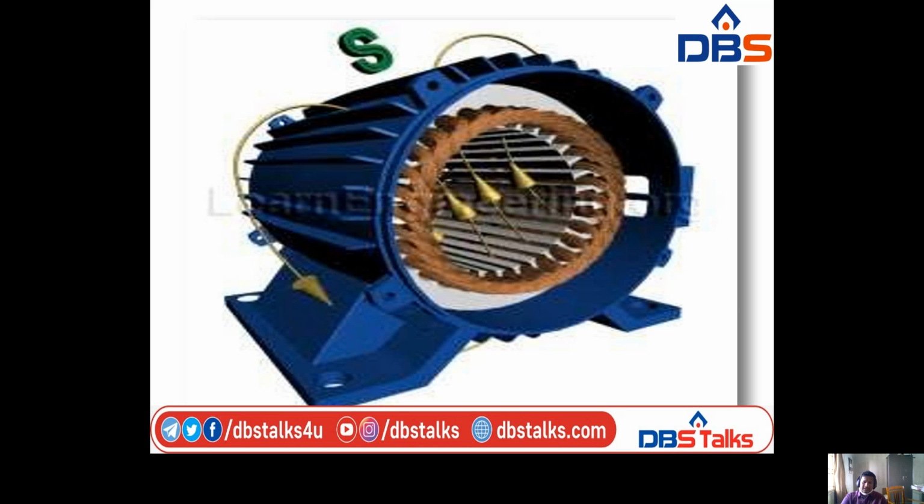So now look at the picture clearly. This is the outer frame and this is the stator core and this is the stator winding and these are the conductor slots. So now conductors are placed in the inner periphery of the slots. Now whenever we are giving the three-phase AC supply, the conductors cut the magnetic flux and develop the alternating flux, that is three-phase alternating flux. That alternating flux is called rotating magnetic field. Look at the arrow mark lines. These are the rotating magnetic field. So this rotating magnetic field may be rotating with a synchronous speed, that is 1500 RPM rated.